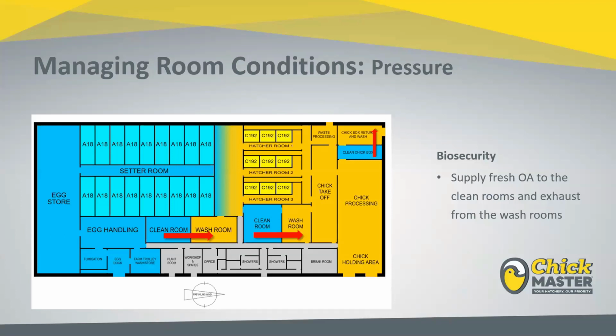Okay. Is it important to supply air to the egg room and set the right pressure inside that particular room, given that the egg room has its own air cooling unit in this particular person's facility? And again, yes, it is important to provide some fresh air to that room because that lets you maintain a positive. Now, is it critical that that is a controlled positive? In other words, do we have a modulating damper on a fresh air with a supply pressure referencing to control that damper? It's not critical that that be accomplished as long as you have a mechanical capability of setting it.